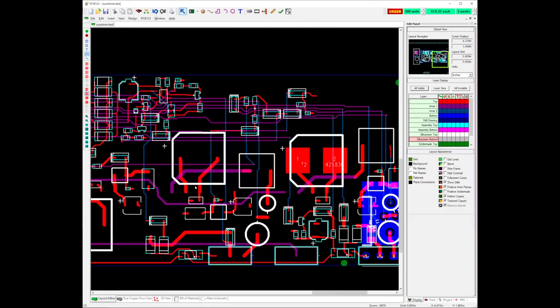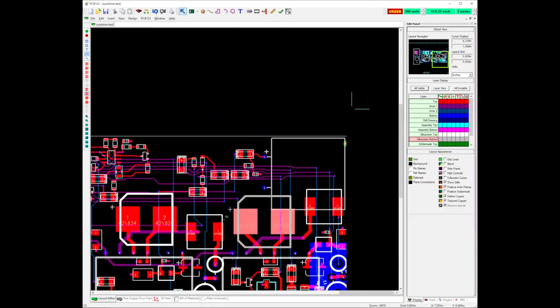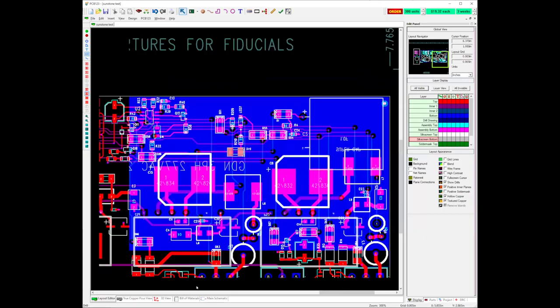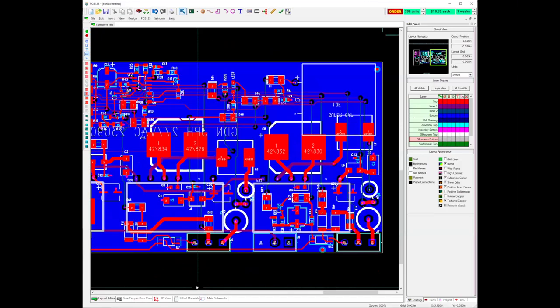Everything's done. I've done this with some pretty big ICs that had a different, slightly smaller footprint, but the same pinout, that sort of thing. As much as 48 pins, and it works just the same. You don't lose all your routing. So for the bigger parts that are a direct hookup, you can do this even for your big ICs and not lose all that routing, which can save you days of routing if you don't rip up your entire board. So that's how I get to that point.